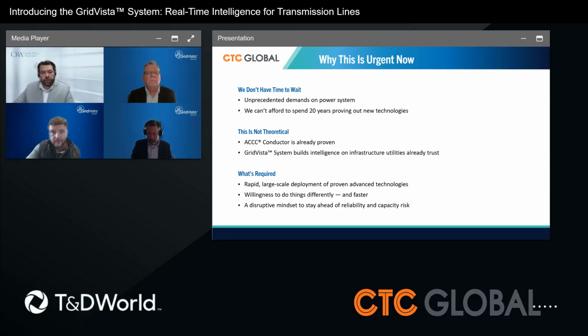The DAS provides real-time sensing for fast dynamic events, things like faults, sudden mechanical disturbances, or abnormal vibrations. The BOTDR provides distributed thermal and strain measurements on a regular time interval, which is well suited for understanding loading, sag behavior, and long-term condition trends. Together, DAS and BOTDR allow GridVista to deliver both immediate event awareness and time-resolved condition monitoring.